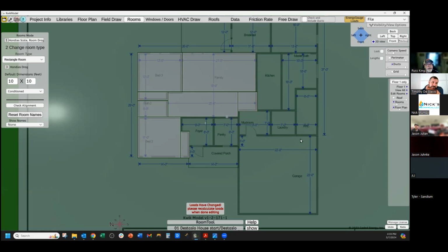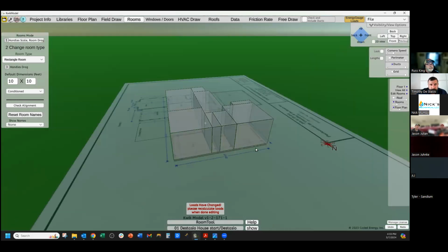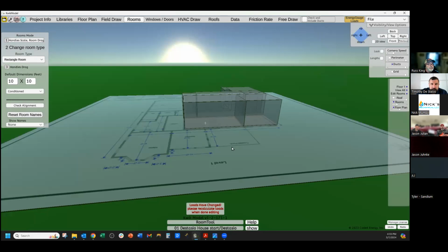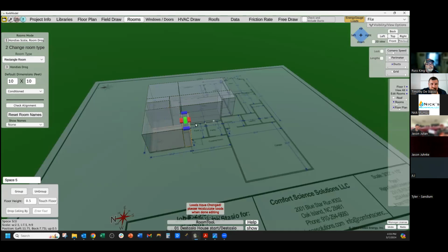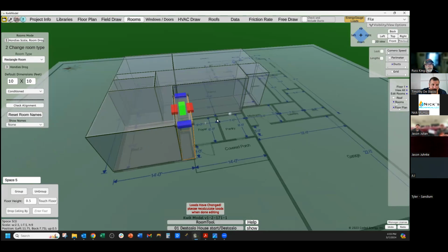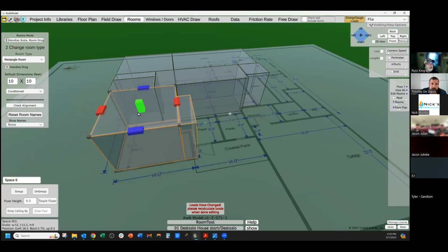Okay, so I just filled that in with boxes, but what I'm actually doing is creating rooms like this. You see how it's doing those rooms, and each one of these rooms has exposed walls. When these little boxes touch each other, you see how they collide. It now knows that it can ignore the wall between those 2 boxes because that's what we call an adiabatic surface. There's no heat transfer through there. And if I group these 2 together, like so, they become one unit and move around together. Now it's considering that a room, and it's going to do the loads on that room by itself.